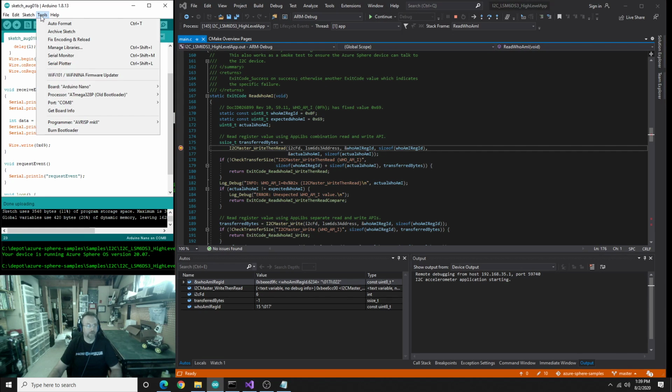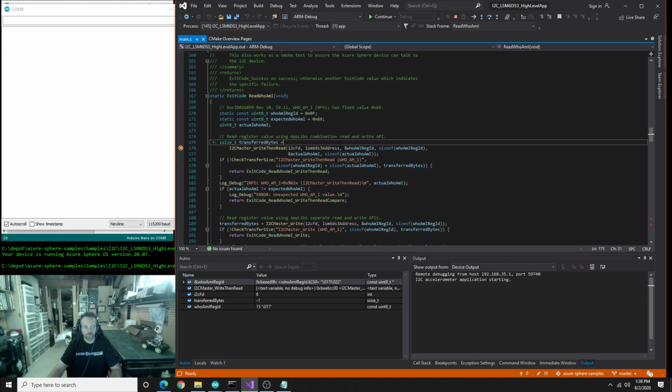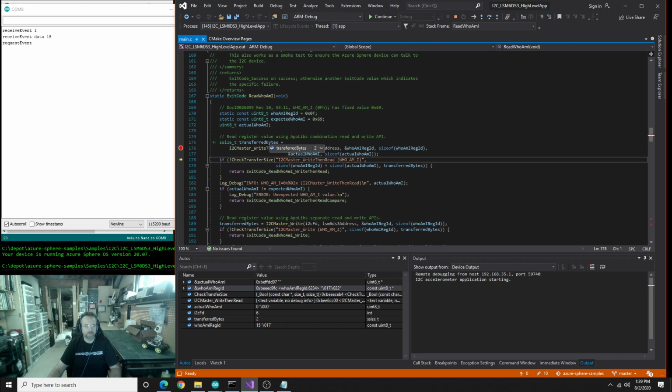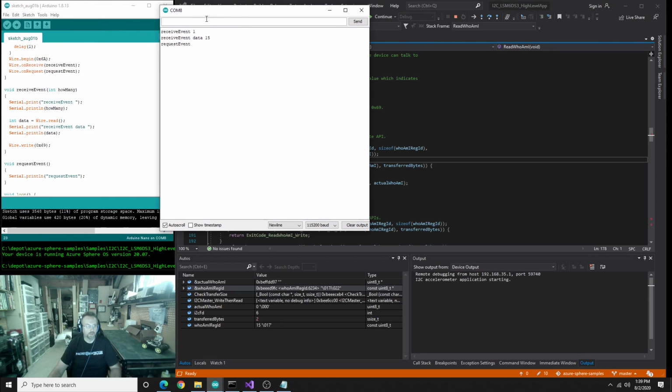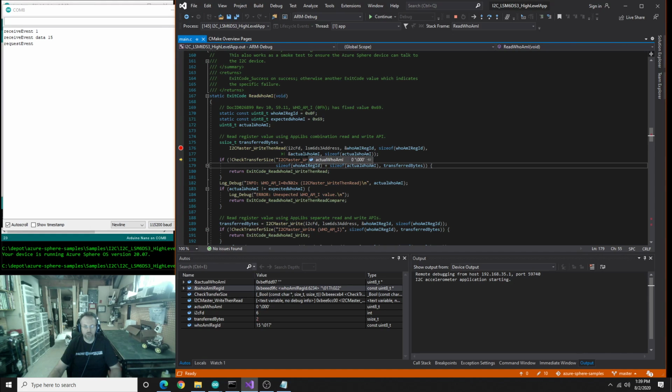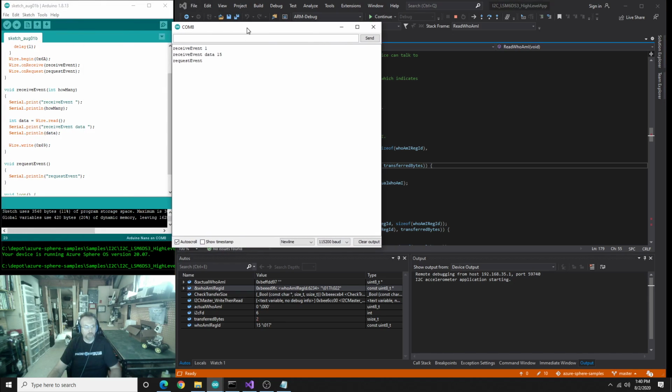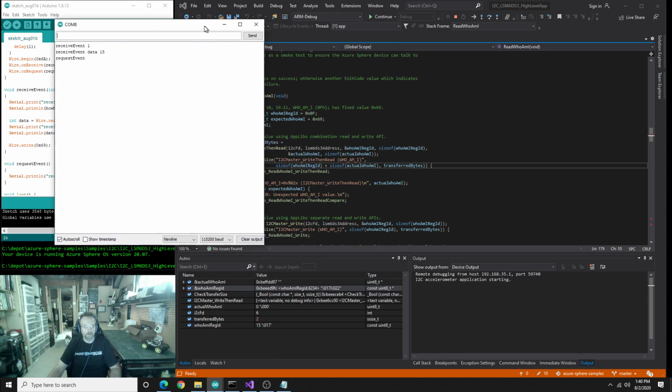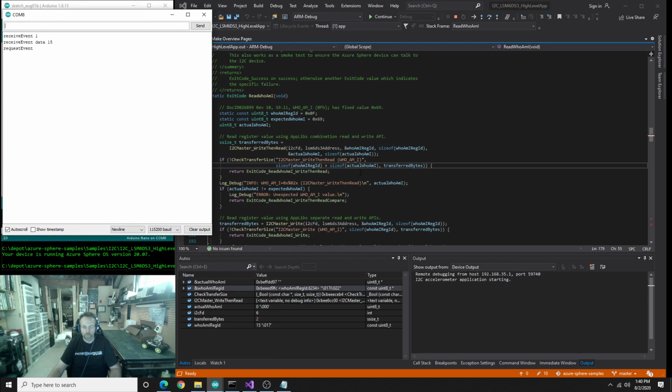Let's go to our serial monitor. Cool. F10. Transferred bytes is 2. We got that receive event of 1 byte with data 15. And then we wrote Wire.write 69 as the answer. And then we got a request event. So what is the actual who am I? It's still 0. And so you're like, but wait, we wrote out 69 in hex, but what we read was we got a 0 back.